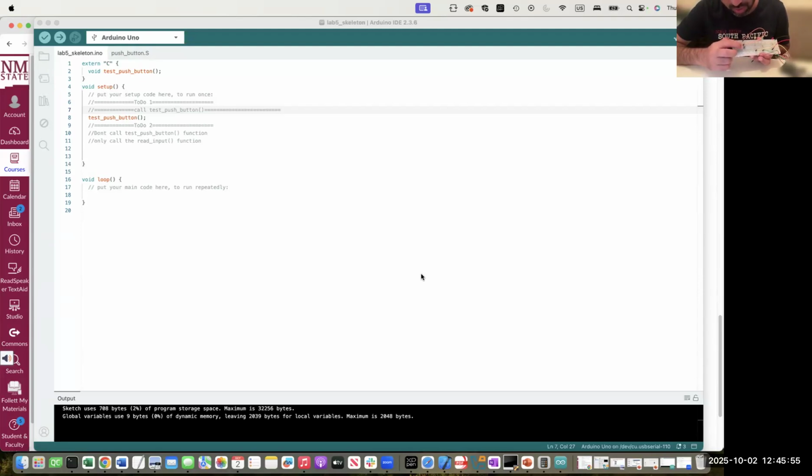If I make a connection with Y and I do not press the push button, and still the controller gets the input value of 0 and turns on all the LEDs, then it means that W and Y are by default connected, all the time. So it means that I need to make this connection to pin 9 of the Arduino board not with the Y but with the Z.